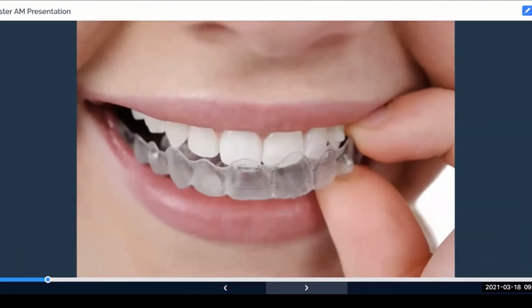One of the classic uses, Invisalign braces. So here's a great understanding of how we can take digital production and really make mass customization, right? That thing I talked about. So you take a mold of the teeth, you digitize it. A technician slowly moves the teeth. They create 30 to 50 different iterations to get them closer and closer to perfect. It would be impossible to make physical molds of each of those and actually create a plastic part that you could send to people. So what do they do? They take those digital files, they send them to a 3D printer. It creates the positive mold. They vacuum form over the top, and they cut out those vacuum form pieces and send those trays. So it's an entirely digital process. There's no physical thing except for the mold being created by the additive technology.